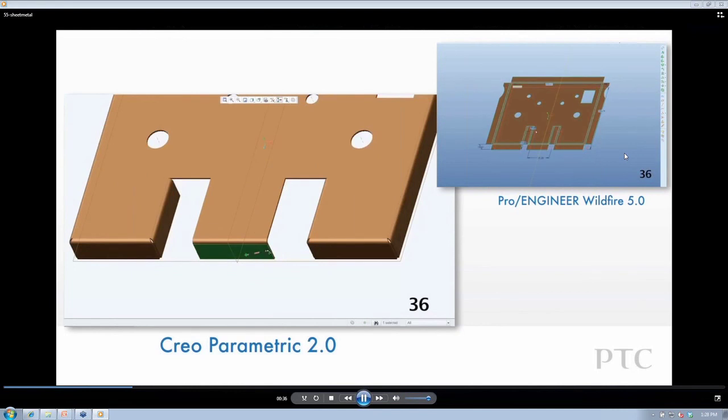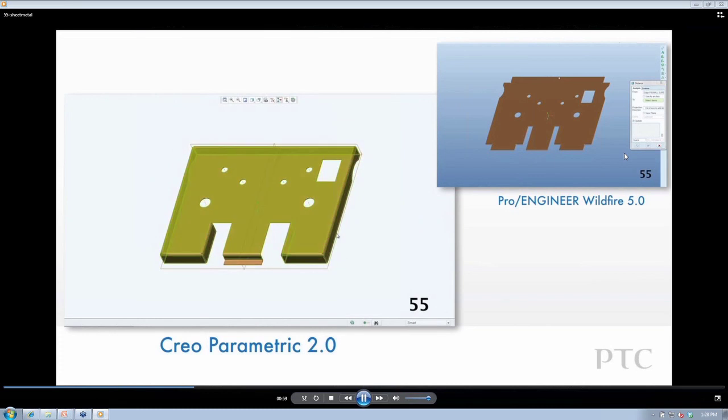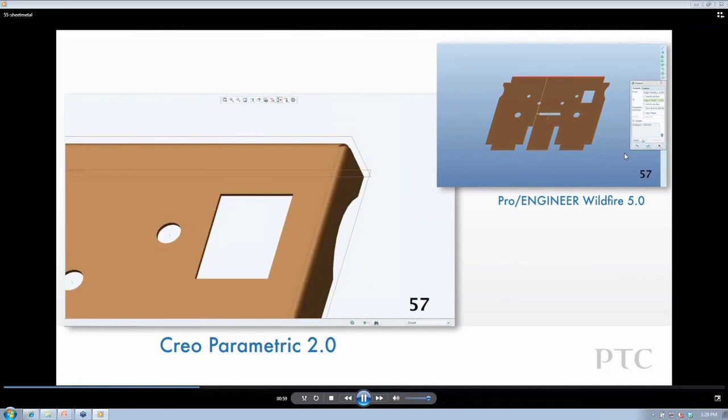Also a new way to make a bend feature. You just go ahead and snap a line on there. You're just basically grabbing a bunch of little snap tools, and then you can type in the values you want. Again, the preview is interactive. You can tell it which direction to go and hit OK. You can also sketch those as well if you wish to.